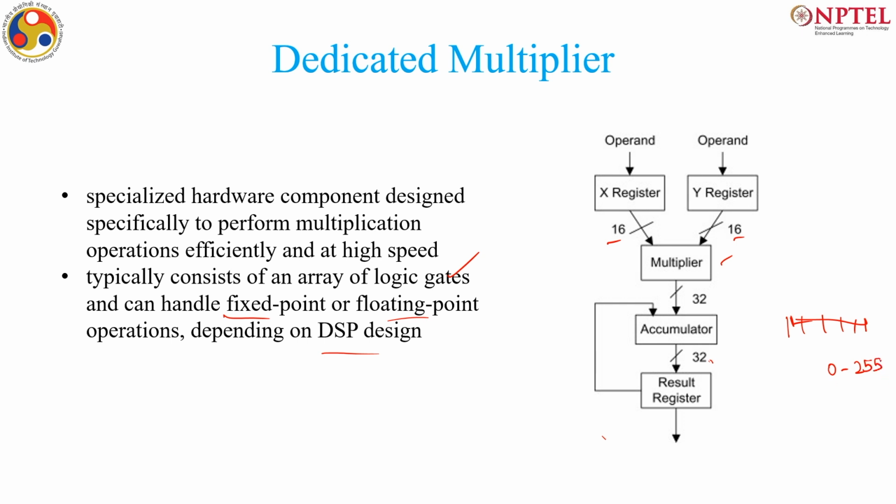But if I have something like 0.5, then in the integer part I can store something from 0 to 127, and the last bit I can use for the fractional part, like is it 0.5 or not. So this point can be placed, and this is called Q format, Q7.1. Then if I use 2 bits for decimals, then Q6.2. So these are Q formats.